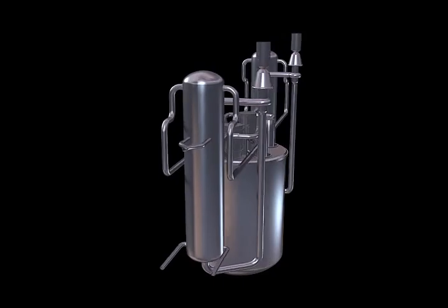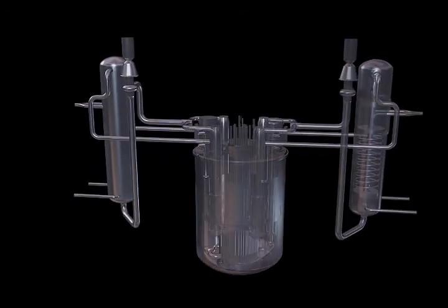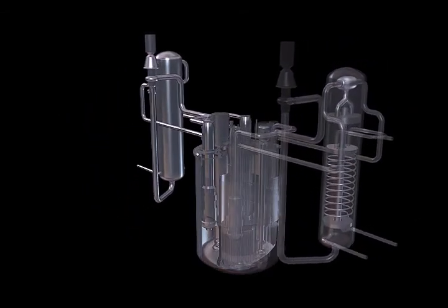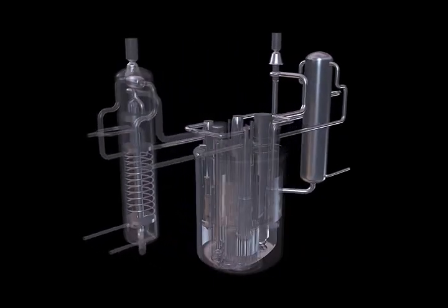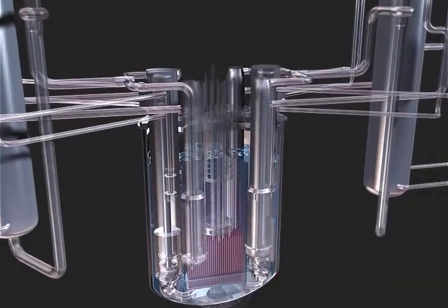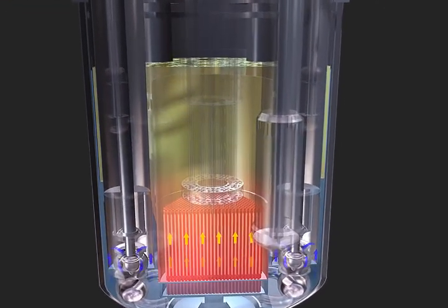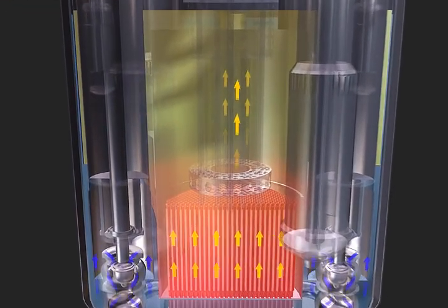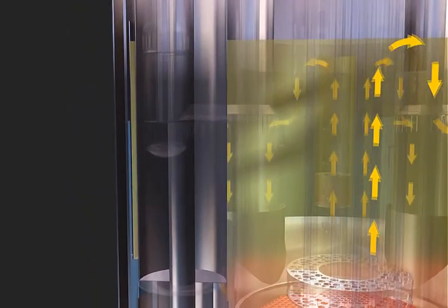At this point, let us show you how this reactor system produces electricity. The main heat transport system, composed of the primary and intermediate heat transport system, uses liquid sodium as a coolant. The secondary system provides the function of electricity production by using a steam Rankine cycle. In order to enhance plant safety, the intermediate heat transport system is employed to prevent an unexpected chemical reaction between radioactive liquid sodium inside the primary coolant system and the secondary water, steam.